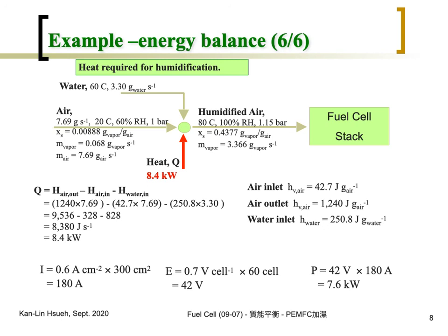So you can see the fuel cell only outputs 7.6 kilowatt, and in order to humidify the air, you need 8.4 kilowatt. Since this heat is more than the power output from the fuel cell, is it worth it? Probably not. But during the fuel cell operation, actually we don't need additional heat for this.